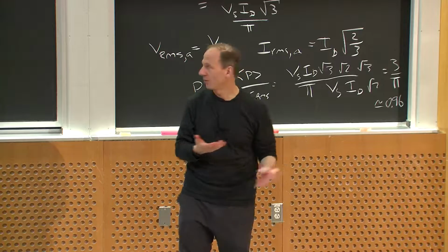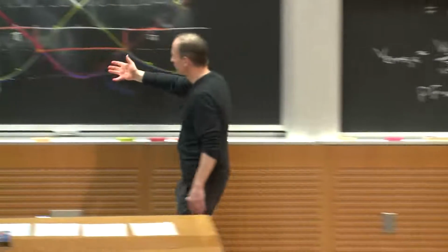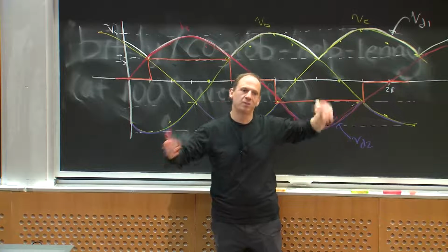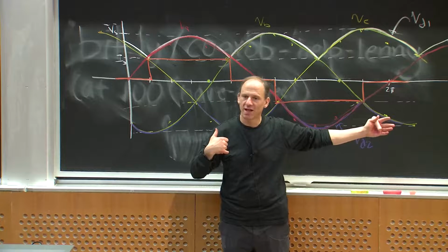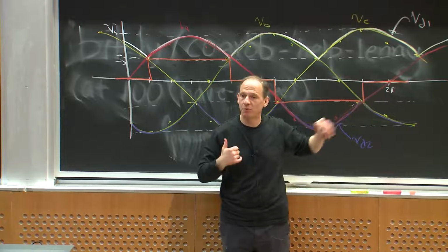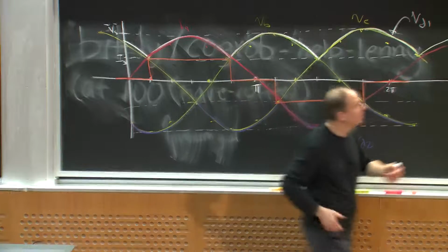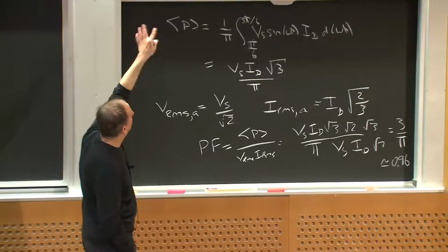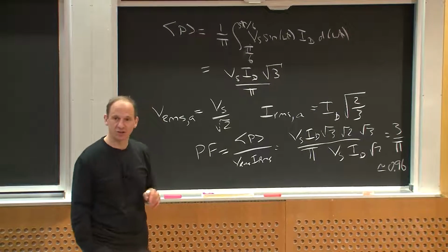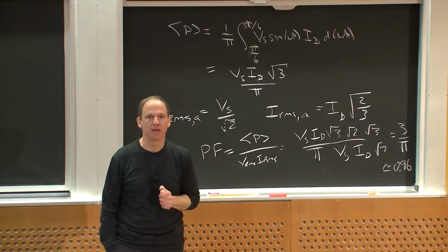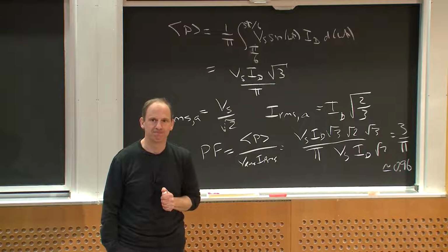I'm not drawing sine waves, I'm drawing this funny waveform, but it's much easier to get close to continuous power. I need much less filtering to give me constant power at the output because I have three phases at my disposal. In the single-phase case, that inductor serves to ride through the twice-line-frequency ripple. I don't need to do that in the three-phase system.